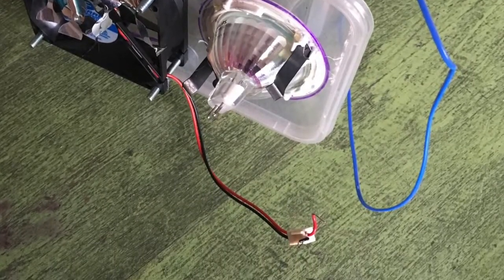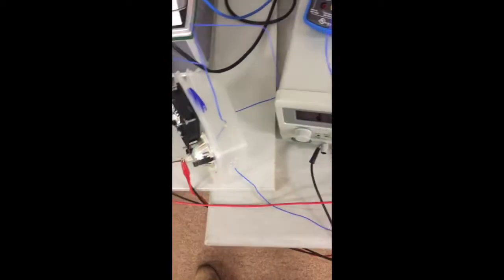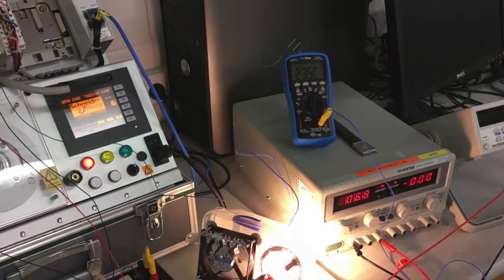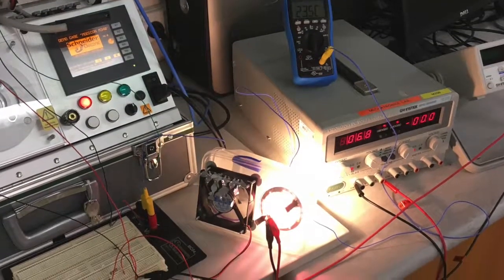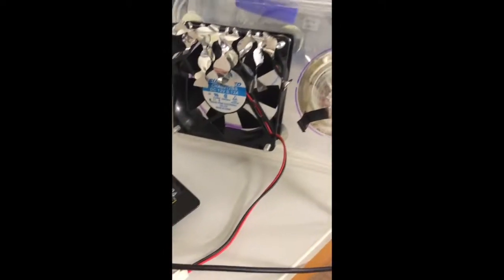To test our concepts, a small model prototype of a greenhouse was made. Heat energy to simulate the sun's rays was introduced to the system via a 50 watt 12 volt DC halogen lamp. This required 4.17 amps to run it at 12 volts, and the current limited benchtop supply was only able to provide 6.8 volts.